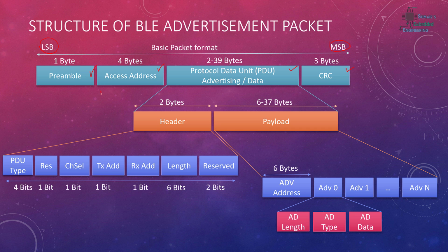For example, if the first bit of the access address is 1, then the preamble is going to be 1 0 1 0 1 0 1 0. So basically it's an alternating sequence of bits, and these changing bits can help the receiver configure its automatic gain control according to the preamble wireless signal strength.